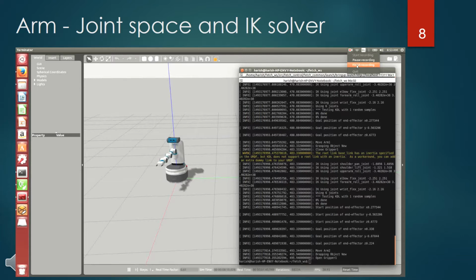In our algorithm, we have created separate modules for different aspects of controlling the arm. For instance, we have separate modules that help us perform IK, trajectory planning, trajectory following, and gripper action. We have created a finite state machine for our task, which integrates these modules, helping us to perform different actions with the arm. This is clearly evident from the video, where we can see the gripper module executing only after the trajectory follow module is completed.